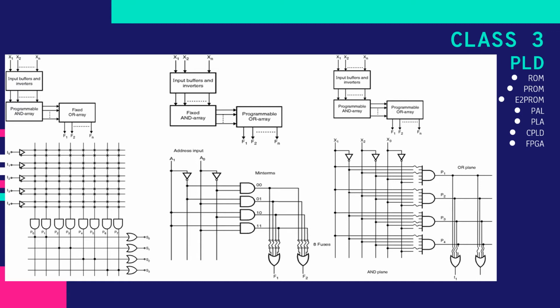Now, your CLBs are the basic repeating logic resource of the FPGA. Its routing resources include the interconnects, and the components of the CLB execute complex logic functions, implement memory functions, and synchronize code on the FPGA. The components of the CLB include flip-flops, lookup tables, and a multiplexer.